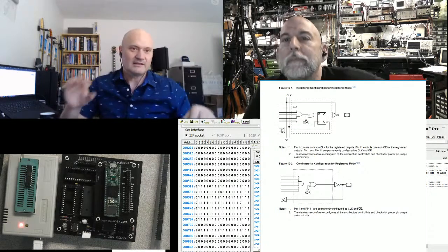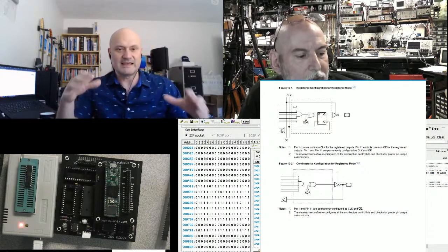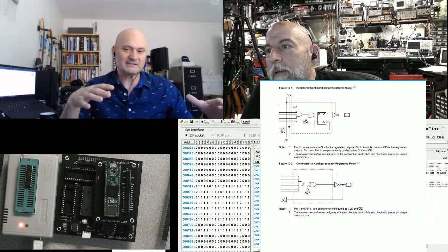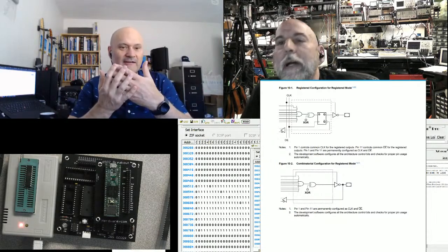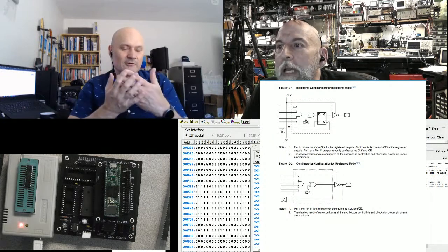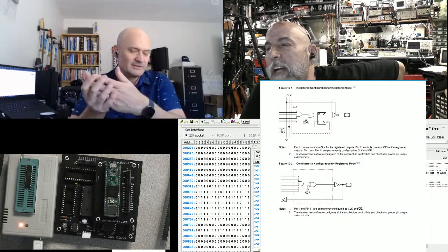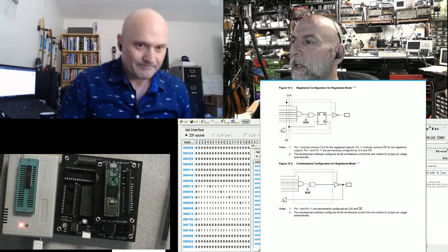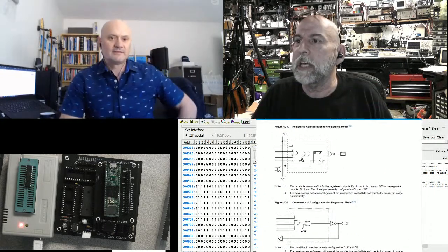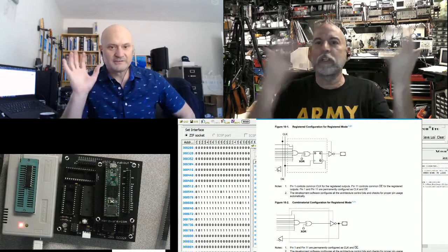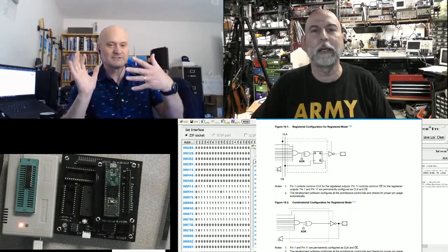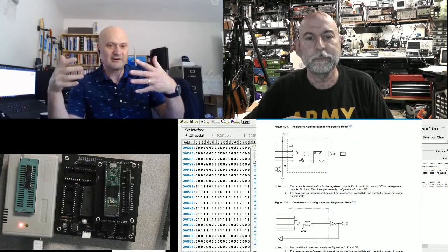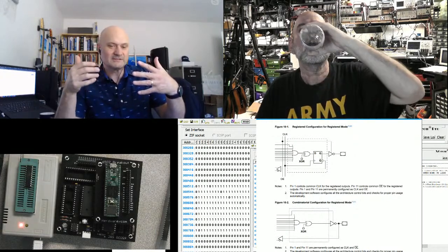Yes. In PLAs, PLDs, GALs, and CPLDs, we're talking about product terms where you have wire ORs ANDed together or ANDs ORed together. And they're actually done with lookup tables in the FPGAs. It's actually static RAM, not ROM, and you have an address, which is your input.